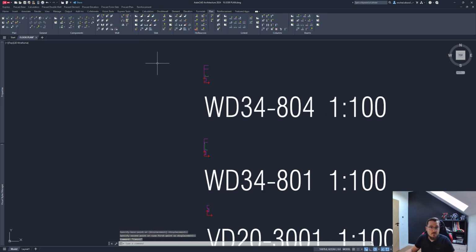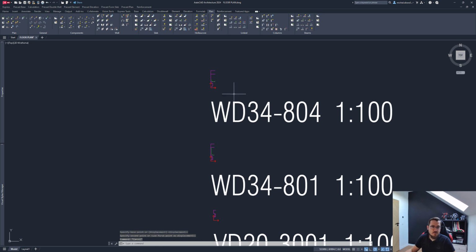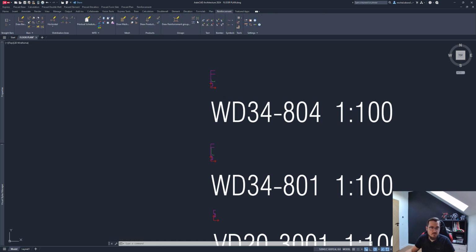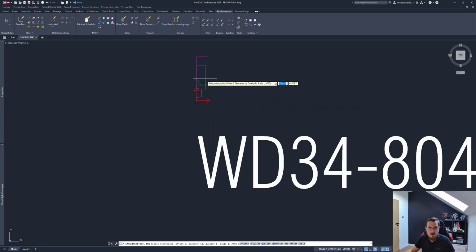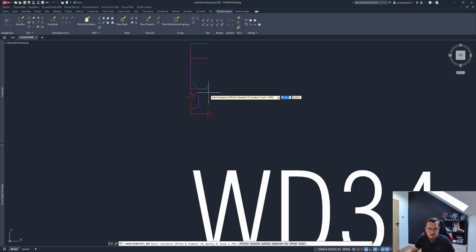Okay. All right. So now, in order to get the reinforcement in, I need to go to the reinforcement tab, and I actually need to create a bar. And that's from the bars tab. What I want to do is specify the dimension of that bar. I can make that a size 10. I also want to apply offsets. Offsets will be my covers, and I'll make that 25 millimeters. Accept that. Or maybe let's make that 20. I think 20 was set for the wall reinforcement. So my offset is like that.